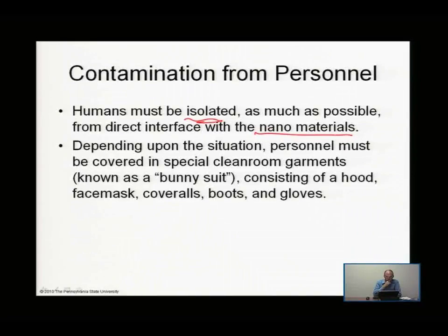If you're going to use a clean hood, then perhaps a full bunny suit is not needed because there's less chance of contamination. But each situation has to be evaluated itself, and you have to make sure that people are not a major source of contamination. If they're walking around inside a clean room, they have to be very, very carefully covered, and their potential contamination impact has to be carefully controlled.